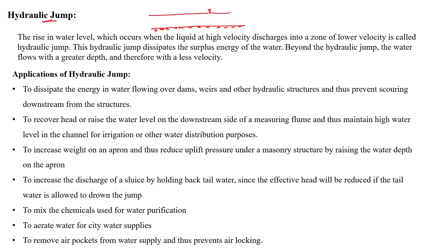When there is a situation like this, water will move at a uniform flow, assuming the channel is prismatic. Let's say there is a hump, or maybe a drop, or a weir type of structure. When the flow takes place over these kinds of formations, the flow properties alter. Velocity may alter, or depth may alter, as well as the specific energy and specific force. All these flow properties will change when the flow takes place over these kinds of formations. So this is a general case.